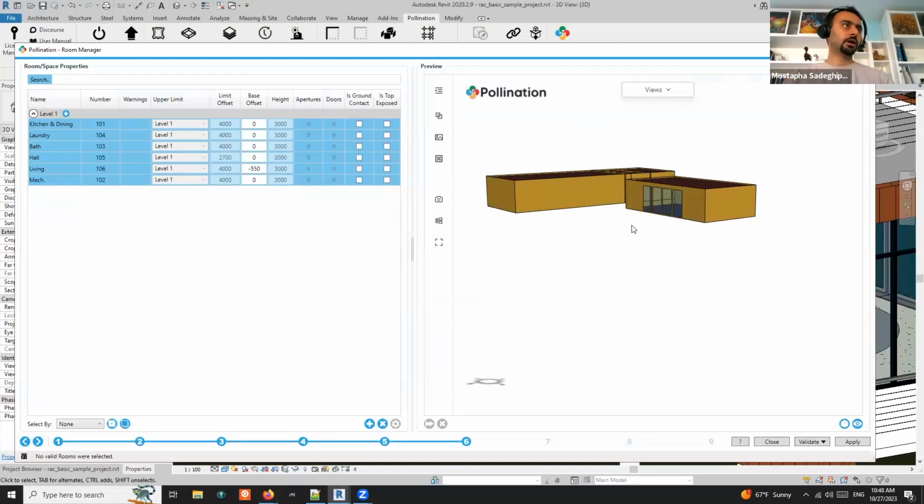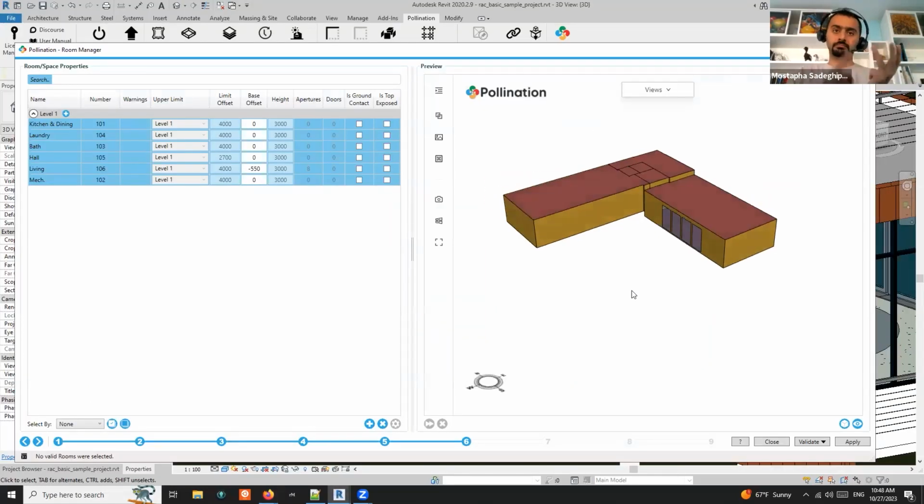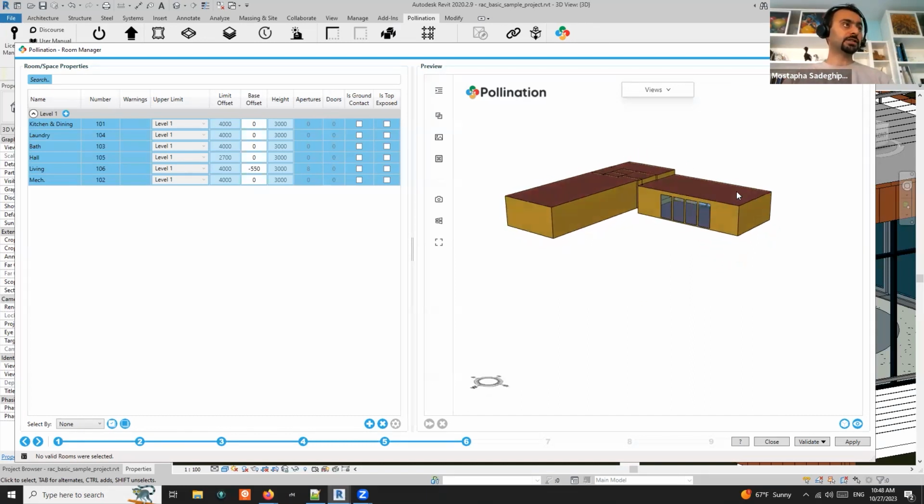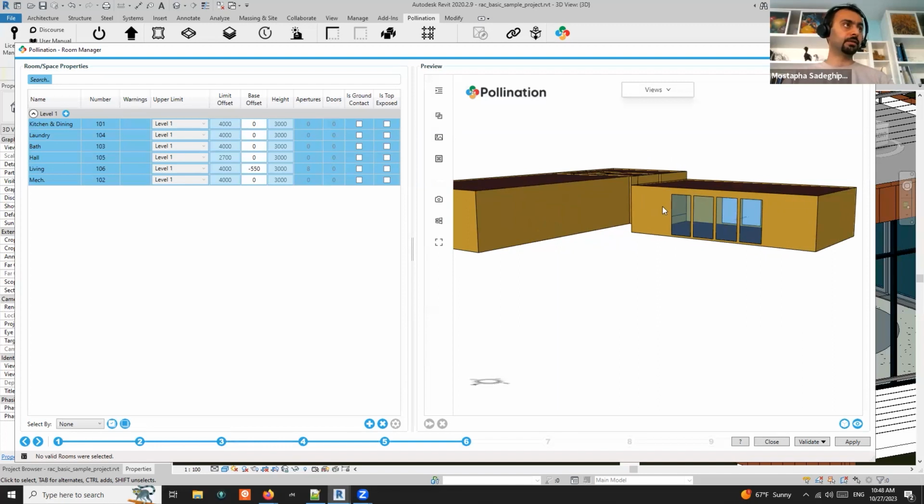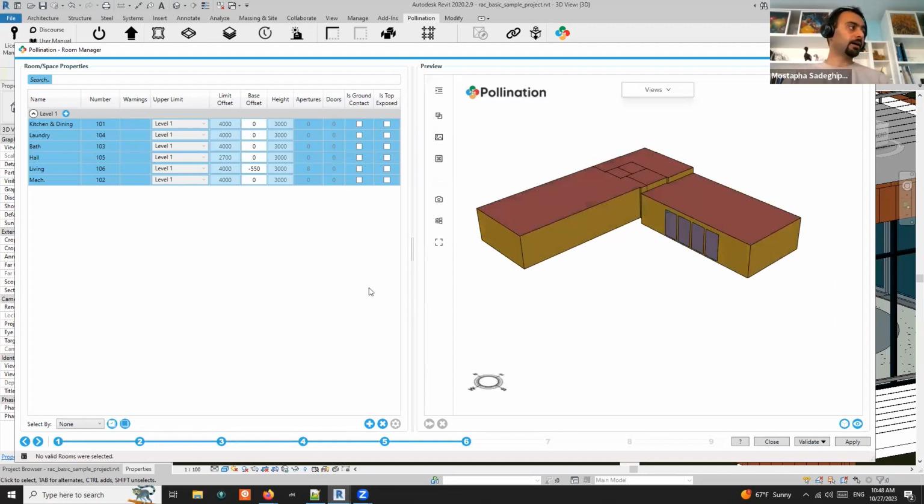So okay, again, review the things. Room, extrude. We know room is space or areas. We check those. We check the columns, and we can use either minimum hole area, or we can make them not room bounding. Then we talked about the apertures and the difference between windows and curtain walls. For curtain walls, it's curtain wall panel. For windows, you either take everything or you can filter by material. And we also talked about adjusting this room, which was supposed to be on a different level. So we said that. So now we have all this.